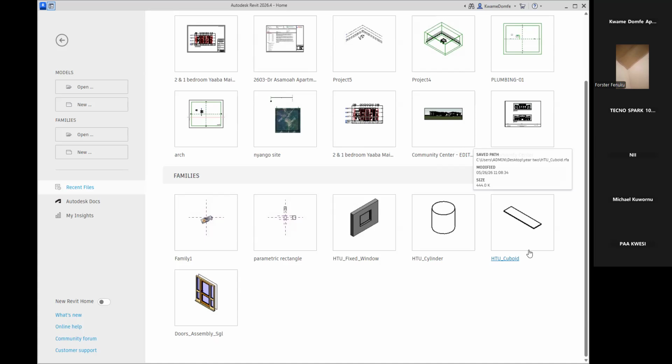You cannot dodge it. You cannot take shortcuts. You must understand the principle and the concept behind it, and then make sure that you do a good model. You've not modeled trusses and you want to see trusses in your section. It won't work that way. So what you do is you don't model the trusses, then you take a section, then you draft the trusses. My friend, how can we be using Revit and then do line work, drawing trusses in 2D? It doesn't make sense. Then go back and use AutoCAD and do line work.